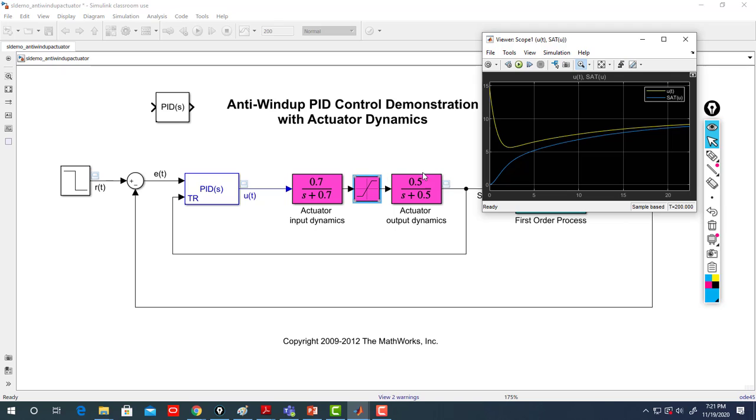If it is minus 10 to 10 and the controller output is high, it will be 10. Maybe it has some dynamics, and that's mostly what happens. So you are applying some dynamics at the input, and it will give you this. So this reflects more the realistic actuator.